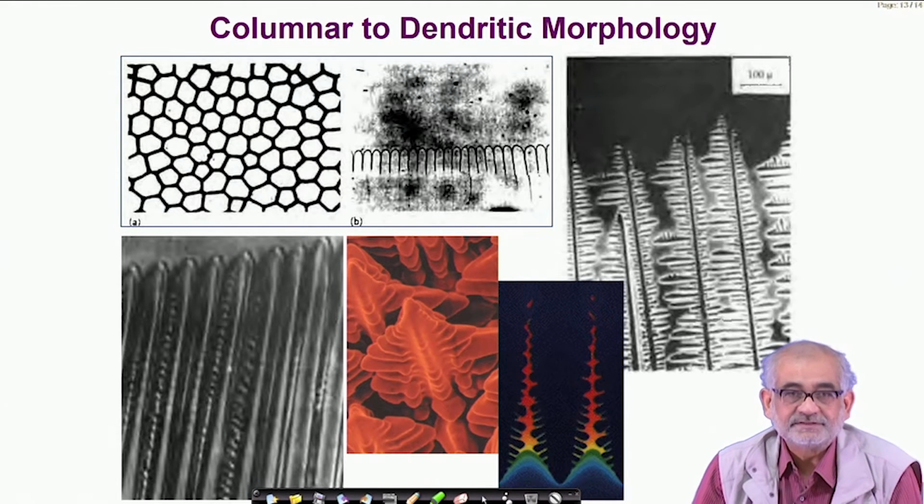For solidification processing, we have to realize that as soon as the hot metal or hot melt comes in contact with the solid mold, heat transfer starts immediately, and that is when the heat transfer rate is the fastest. So, we first get very ultrafine structures, followed by gradually rather coarser structure, and finally in the middle we are likely to see such equiaxed zones where the tendency of growth or the rate of growth of the crystallite in all three directions would be about the same.